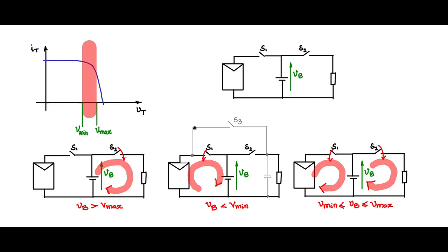So one can have this kind of a structure to see that during the time when the battery is low, the PV panel is charging up the battery and S3 is connected here, and the PV panel is also supplying to the load. But understand that this S1 is a unidirectional current flow. Current will not flow out of the battery and again through S3 into the load. So that is one caution that you have to apply.